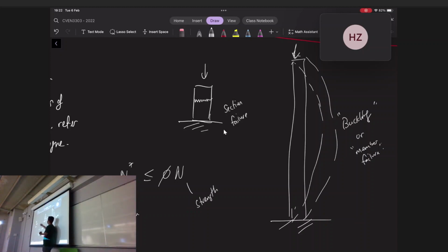At 400 kilonewtons, it'll fail through section failure. That's a study of the material. So once we calculate that, we know, okay, this particular column, at 150 kilonewtons, it'll fail through buckling. Right? So, for the right-hand side, once we go through our different failure modes, what do we pick? The failure mode with the largest load or the smallest load for this side?